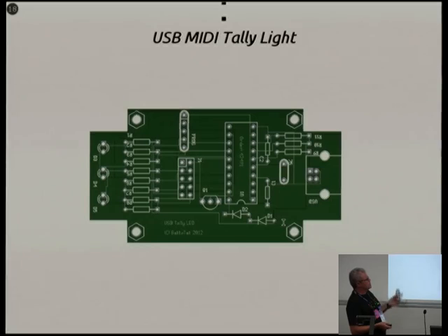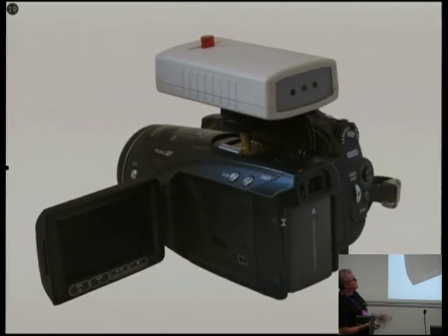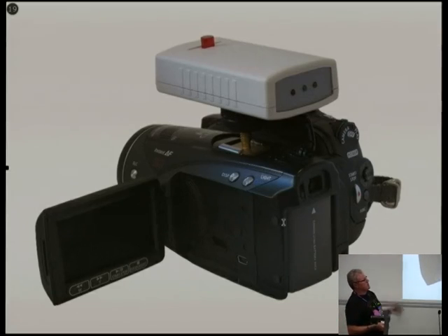Again, pretty simple circuit, tiny little board. I think about $20 to make each one. Really basic. And there's an example of it with one of our cameras. The 3 at the back we're not really using at the moment because DV Switch doesn't support signaling on them. It just tells us the main tally. But the intention was to extend that and use those for indicating other things like your camera's out of focus, or we're about to switch over to you, make sure your camera's steady, that kind of thing.